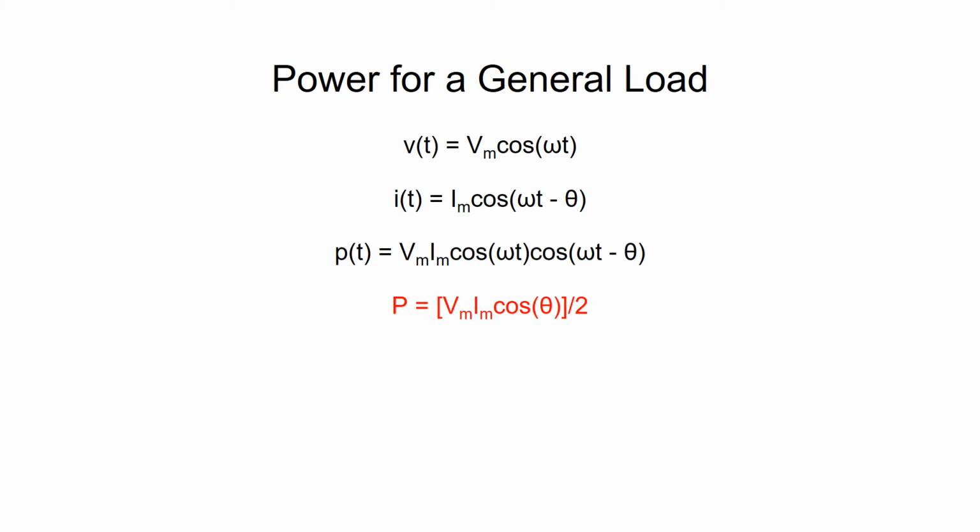While when the load is purely inductive or purely capacitive, theta is either 90 degrees or minus 90 degrees, and the cosine of both of these angles is 0. This confirms what we already know, that the real power used by both such loads is 0.